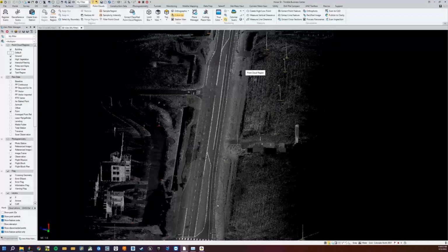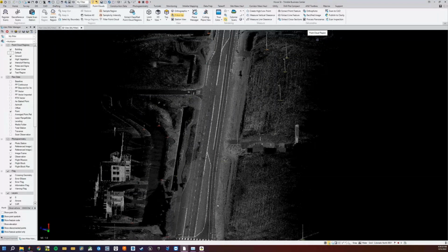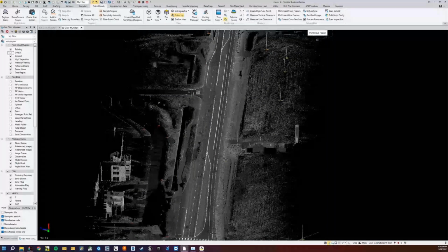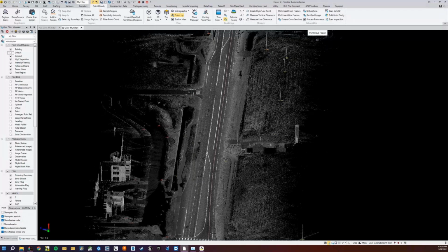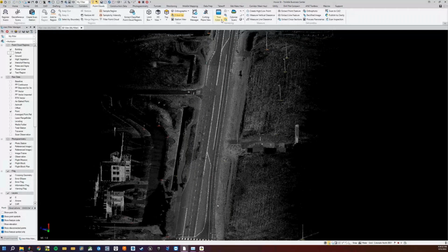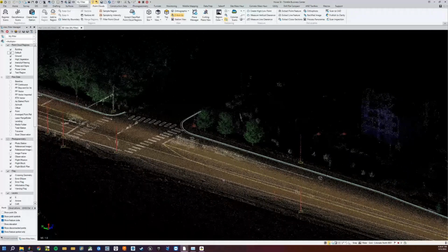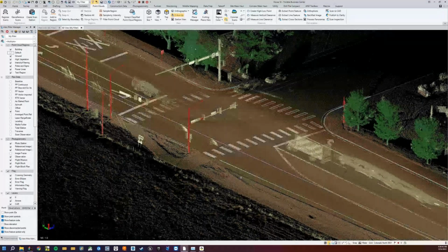If I'm trying to turn a point cloud into extracted assets, or a course as-built of where everything is, my workflow is generally to classify the point cloud regions, which you can see I've already done on this project. So you can see I've got my buildings, my trees, my poles, all that. You can see the default region was full of vehicles and traffic and stuff like that. So I'll turn that off, and we've got everything cleaned up.